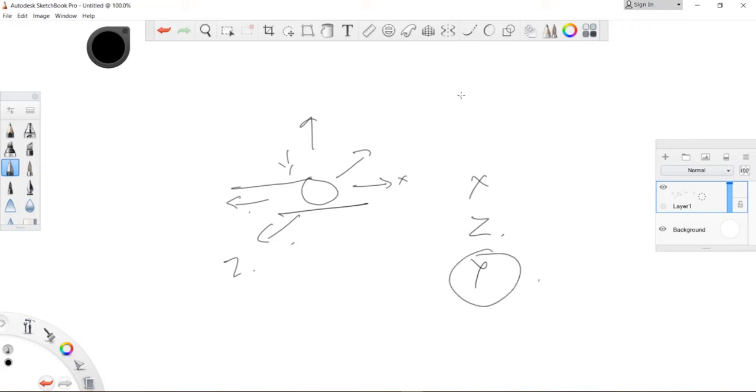Similarly, for the roller support, you can rotate in the x direction, you can rotate in the z direction, or you can rotate in the y direction as well. Rotation in the y direction means rotation about the y axis. Similarly, rotation in the z direction means rotation about the z axis. So rotation about y axis means that, so this is our roller support. Okay, this is the ground and the y axis is the vertical. If we apply the movement like this, this will rotate like this. So this is the rotation or my movement.